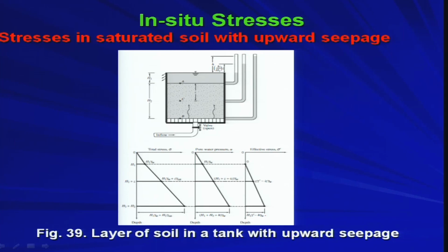Now, in the same problem, as I told you, we are considering the upward seepage, that means we are opening the valve, so water is moving upward. In that situation, see the head difference, this is the top surface of the water, because after that water will be spilling out. Now, the head loss happening for the water when it is traveling from the bottom surface to the top surface is given by small h, right. So, that is your head loss.